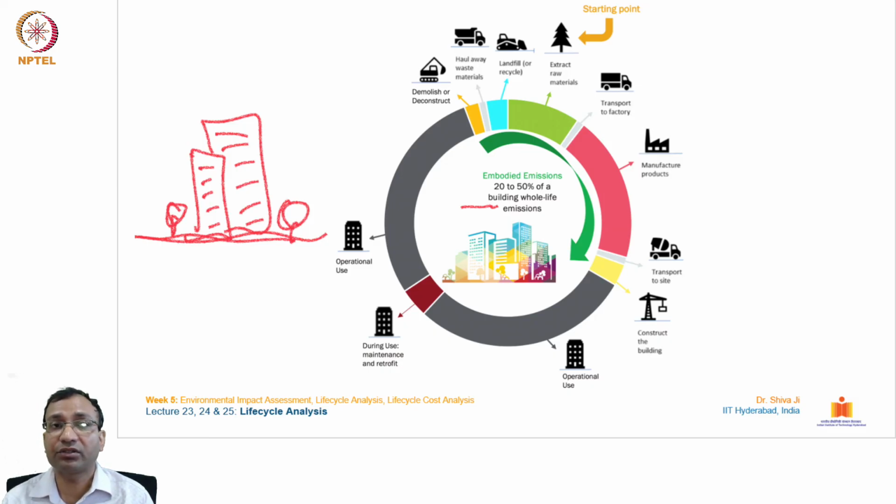At the stage of demolition, the rubble material is taken away from the site for extraction, and some of the bulk, the concrete part, the grit, cement and sand part, goes to landfills, because till now there are no systems efficient in economic terms available to recover the concrete part. There is still some research and experimentation going on to deal with that. But the extracted metal parts and other components such as glass go for recycling. And this is how the components of the building come to an end.